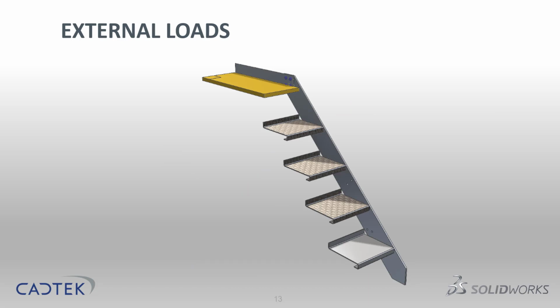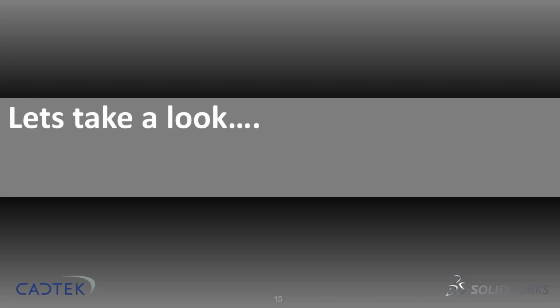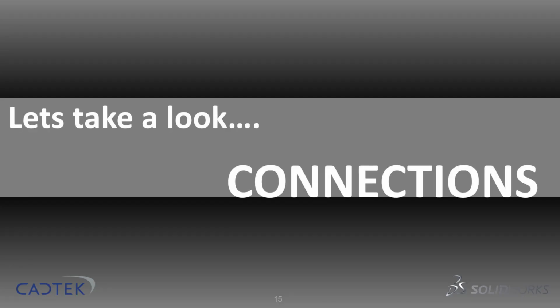We need to finish this off just finally by putting in that external load. Going back to the drawing standards, it's actually 2000 newtons applied per meter squared over the top gantry. In other words, 2000 newton per meter squared of pressure on the top face as well. Let's go back to SolidWorks and build these connections.